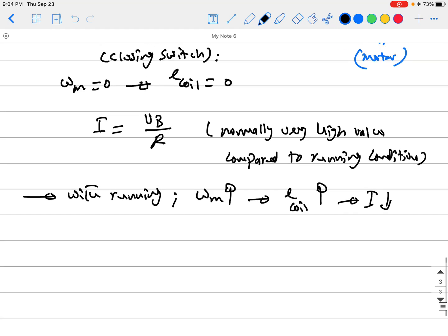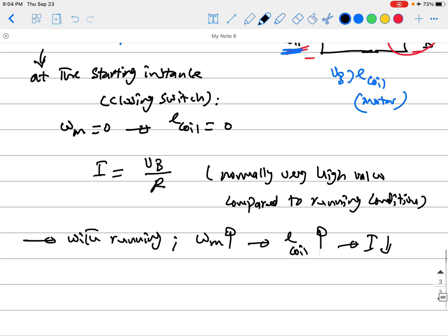That's the very high amount of current the motor draws at the starting that we always try to deal with. Even it bothers the power system guys when planning the protection devices of the power system. If they have a big, huge motor in an industrial facility and this motor is trying to start, it may cause some disturbance in the system if this problem is not mitigated. So that's a very important thing to have in mind, guys.